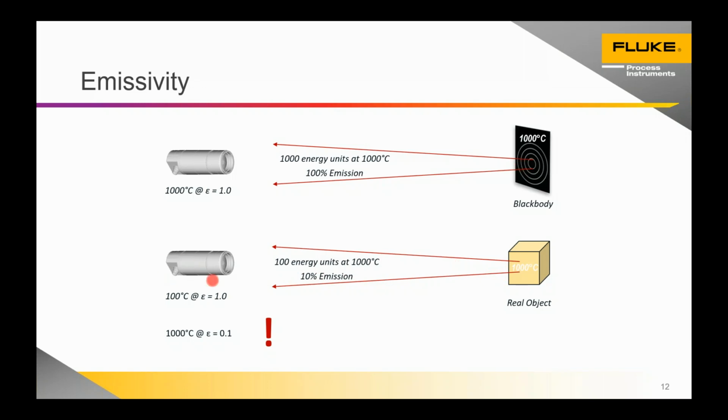The sensor has got an emissivity of 1, and the reading in general cases would be 100 degrees. There's a whole wavelength temperature analysis that on some devices would mean that wouldn't be 100, but generally as a rule of thumb, 90% loss of energy, 90% loss of reading. That wavelength argument tends to be mostly for low temperature units.